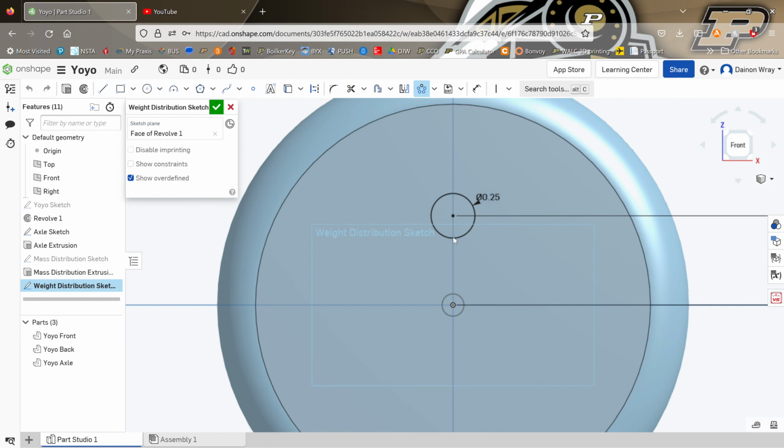and now I'm going to click on our feature here. Very nice. And it automatically recognizes that that point is what we want to revolve around. So I don't really want 3, I want to add more weight. So let's do 6. Let's do 6 instances of that feature, and it will copy it 6 times, and it will create them equidistant from each other. So that is a very handy tool, and it saves a lot of work.